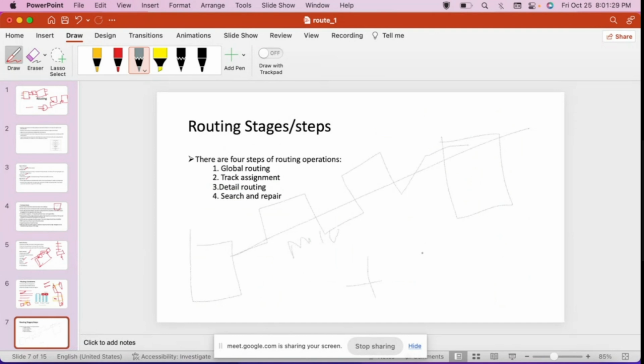Now, metal one is generally M10, and M10 is defined as a horizontal routing, so M10 has to route horizontally only. In some cases you can constrain this M10 as vertical, but then you have to go for less routing. If you want to route a minimal distance, nothing but minimum length, you can make M10 vertical. This is called a preferred routing direction. You can make non-default also, and that has to come from your technology file.